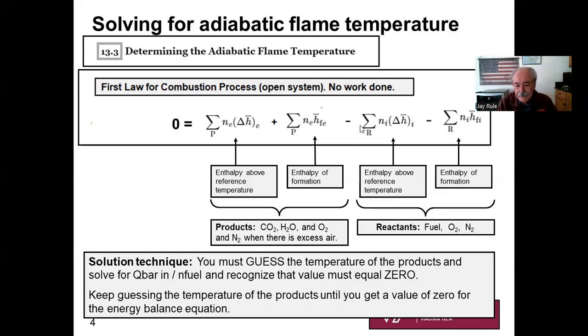Another thing to remember is that these delta H blocks coming in, delta H, the temperature of what's coming in relative to the reference. Exiting, the enthalpy relative to a reference temperature. So do you see that this delta H term depends on the temperature of the exhaust? This delta H term depends only on the temperature of the air and fuel going in.